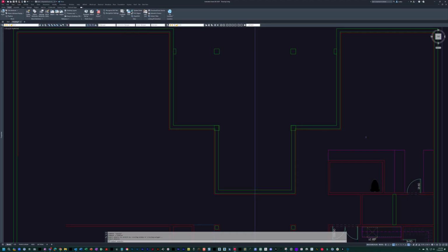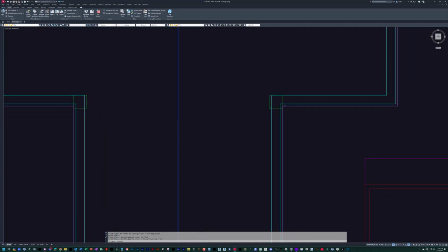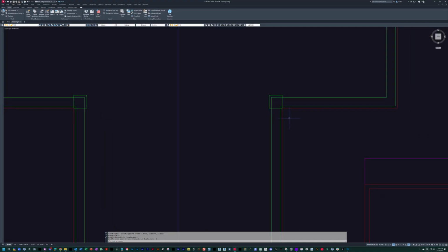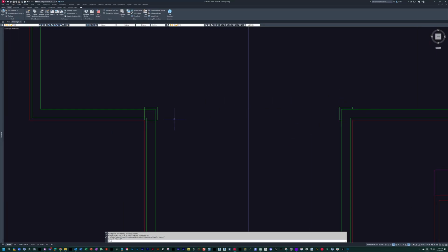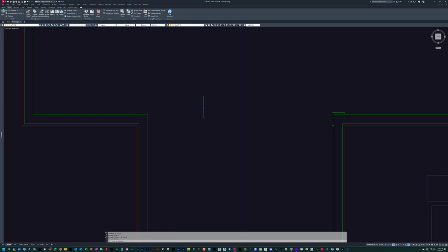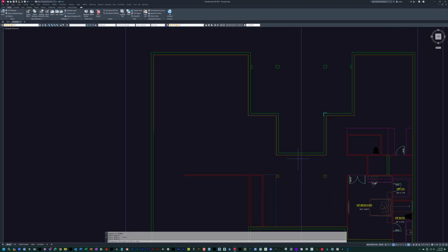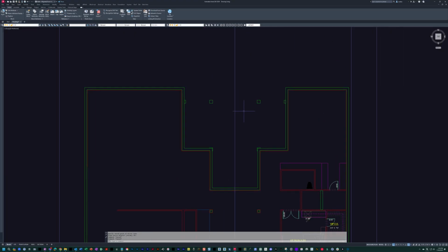So I'm going to actually grab these walls, stretch it, but I'm going to remove the columns from this stretch and then stretch this down 2 inches, and now you can see if I trim based upon this corner, now we just have that outline of a column, and that could actually be kind of nice and make things look like they kind of all fit in.